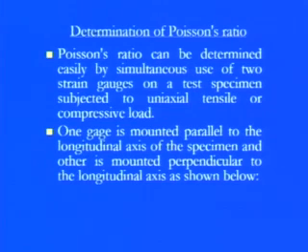Because if you just go for the physical sense of Poisson ratio, we will find that if we have a tensile bar and there is an extension towards one direction, there is one strain gauge which we need to measure the extension, but there is a contraction in the perpendicular direction. So, we need to put a strain gauge in the other direction also to measure how much contraction is there in the other direction.